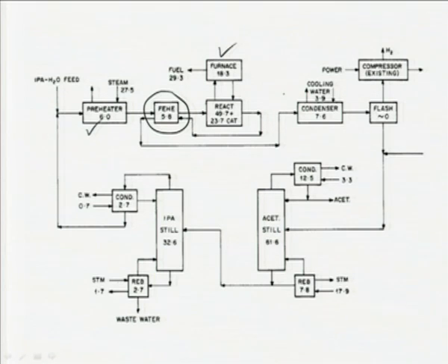So, we recommended, based on the cost that was given, the cost of the steam, the cost of the fuel, and then the annualized capital cost of the furnace and preheater, that we have to increase the size of the feed to effluent heat exchanger, so as to have better heat recovery and heat integration into the process. That would bring down the operating cost.